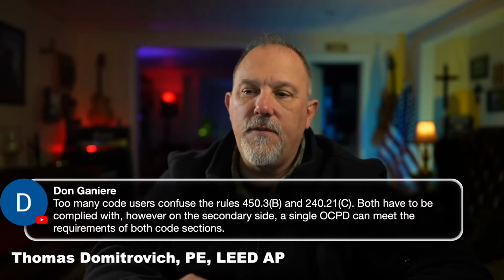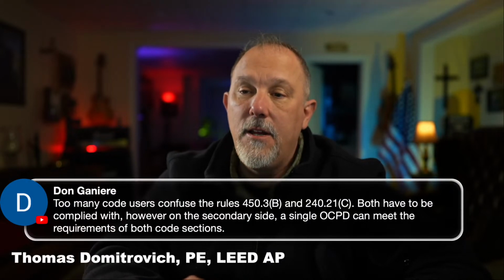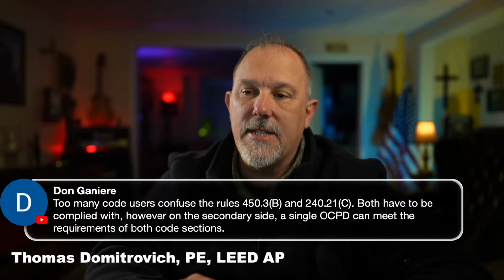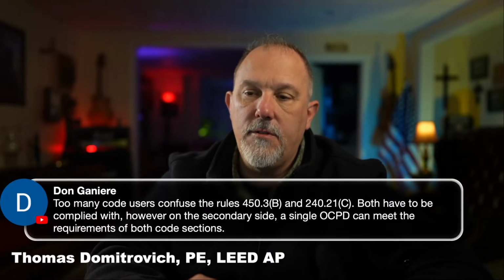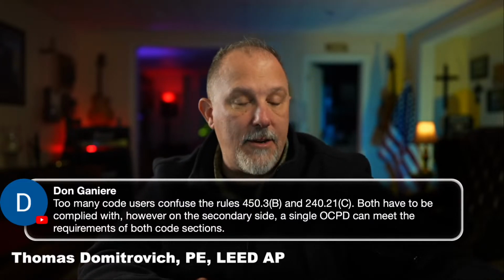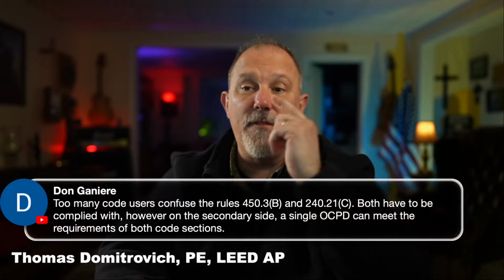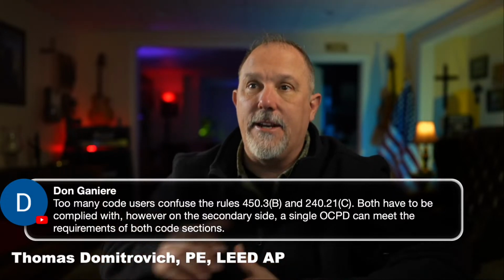Too many code users confuse the rules in 450.3(B) and 240.21(C). Absolutely. Both have to be complied with. However, on the secondary side, a single OCPD can meet the requirements of both code sections. Absolutely. If you put an overcurrent device on the secondary, and 408, can't forget about 408. Can't forget about what it is you're protecting on the secondary.